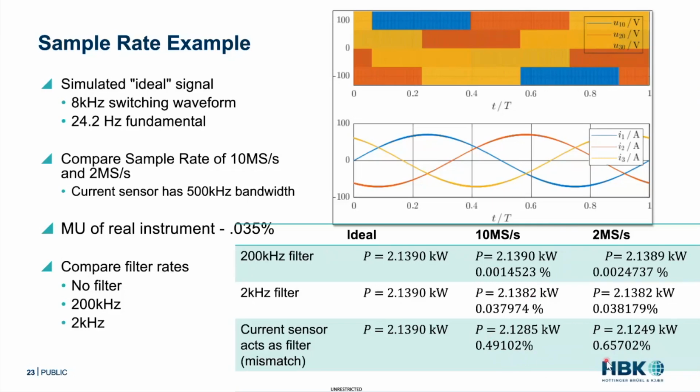And that's because now with different filter rates between voltage and current, we're adding a ton of phase distortion. And this is going to be problematic for your power calculation because phase is quite important. The phase between your voltage and current is quite important. So filter at a rate that I like to include a lot of those higher end harmonics. I even like to set my filter so that some of my switching gets included because you're going to get just a super accurate result.